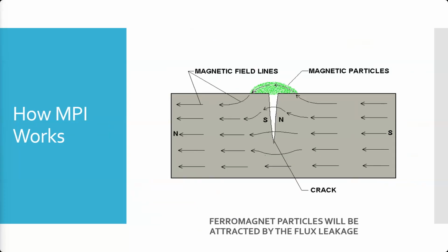So you tend to have magnetic particles gathering down in a corner, an inside edge, or in a hole, like the bolt holes you saw at the very first slide. There's a magnetic field jumping across those bolt holes. So not only does the fluid tend to pool there in the first place, but there's a magnetic field that's stronger inside that hole than there is surrounding it.